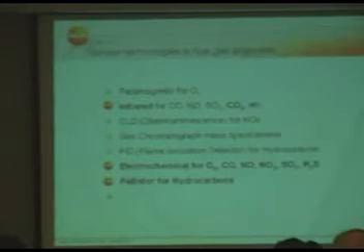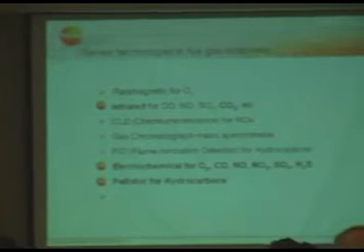But at a cement plant, it's different because during the process where the cement is being produced, a lot of additional CO2 of the material is being produced and emitted to the flue gas. And then you need to divide between the CO2 coming from the fuel and the CO2 coming from the material. And therefore, you have to measure the CO2 directly.